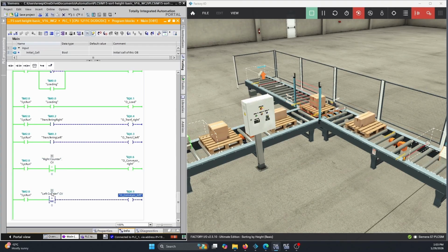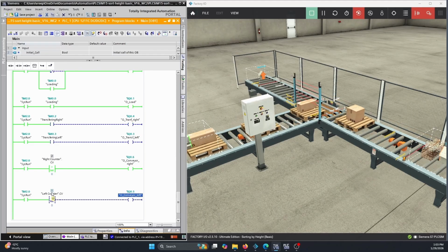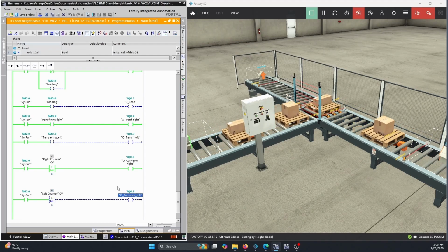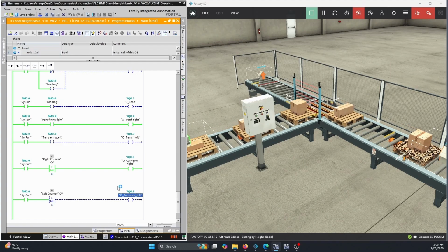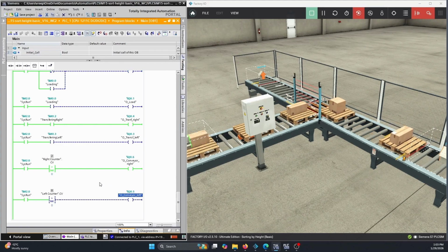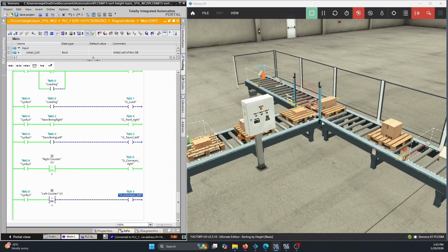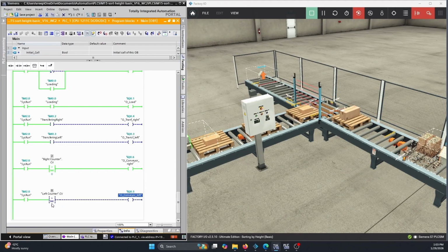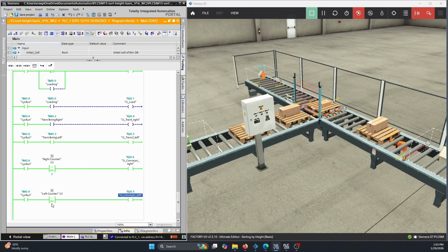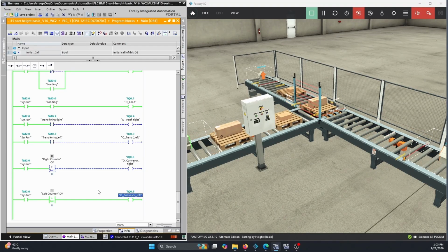Here there's a value of 0, so the left conveyor is not on. We're getting a plethora of larger boxes coming through. There's a small box that's coming through, so at that point the right and the left will most likely be on because we'll still have pallets here on the right and left is coming in. Nice. Count is 1 now, so now that left conveyor turns on.